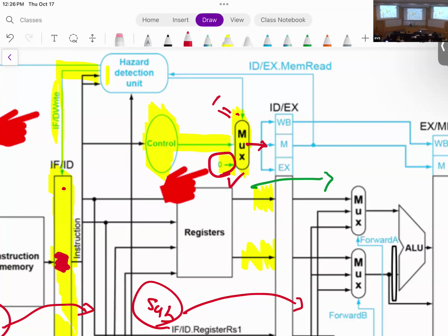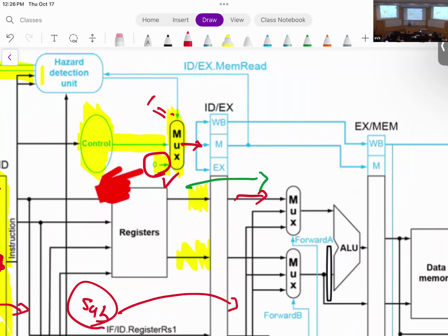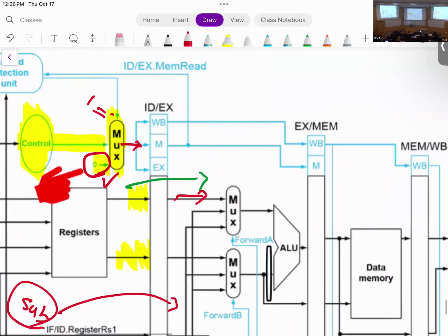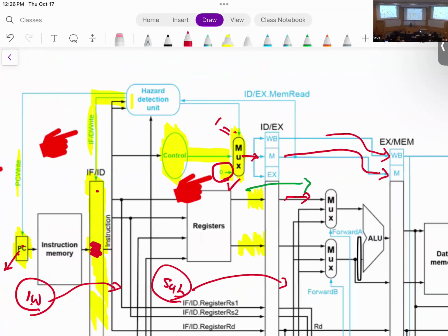And as you will see, once everything is 0 here, there will be operations, but these are what we call a no operation. So there's an all-zeros operation. There will be subbing two zero numbers together. I'm not going to save anything and so on and so forth. And then this will move forward, right? So as you can see, this moves forward to the mem stage and write back stage and so on. So inserting a bubble is as simple as replacing the control signals with all zero signals. Okay? So that's the main two things that we do in the hazard detection unit.